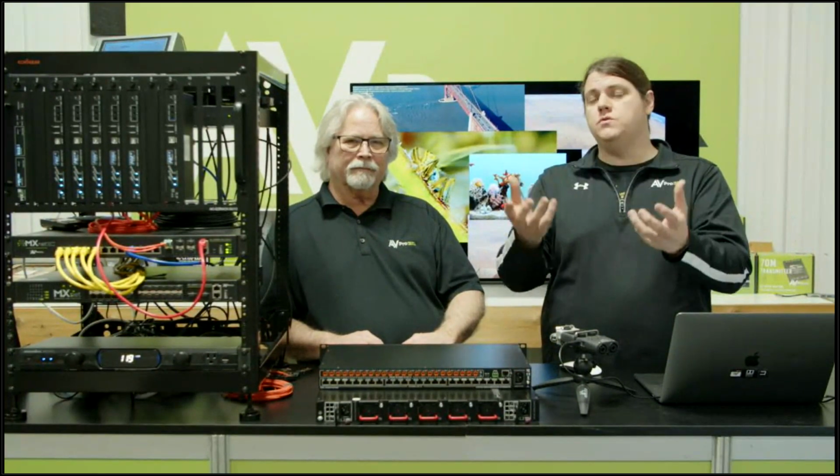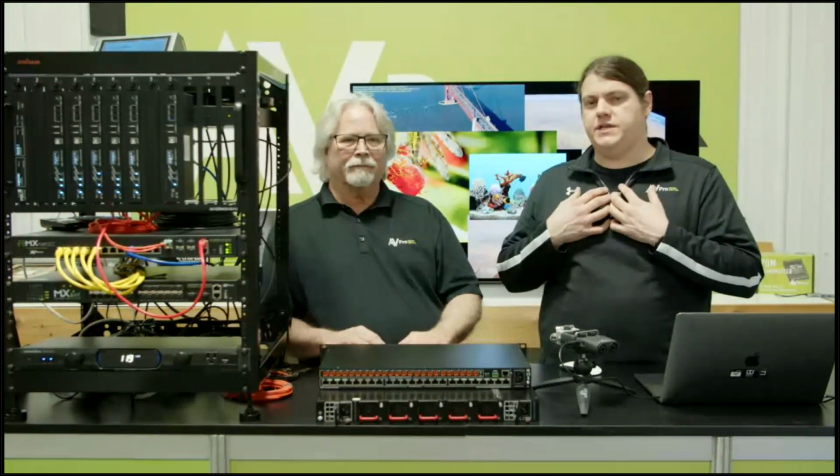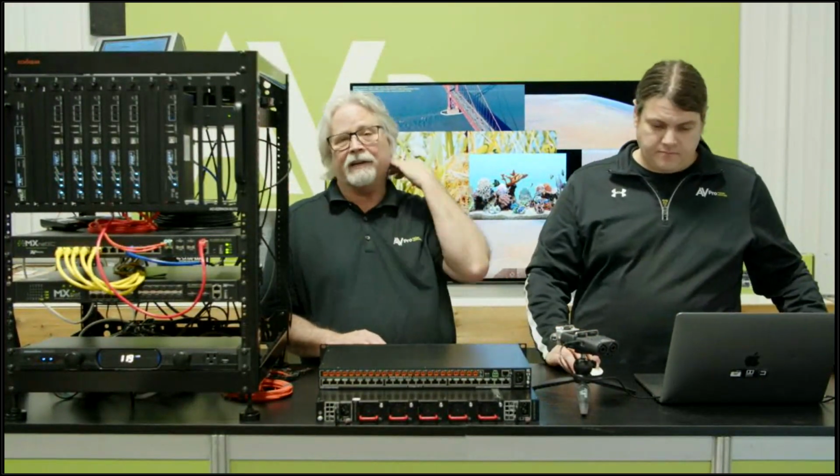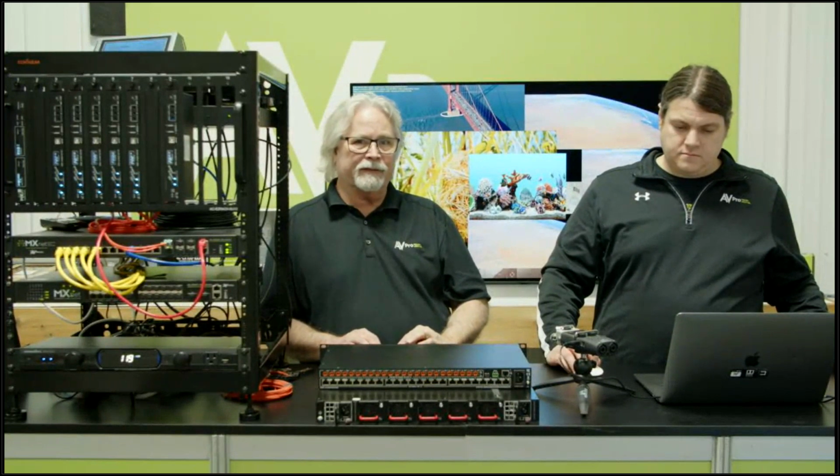Now, if you have something in and you want to try it, by all means you can, but we cannot guarantee the stability of our system or for your customers. We can't guarantee you're going to get the same quality, or that you won't have dropouts when you use a lesser type of cable. So that's just something to keep in mind. With Cat 6A, you can go 100 meters, 333 feet, which is a pretty good run for a lot of places, using the 12C, which is perfect.